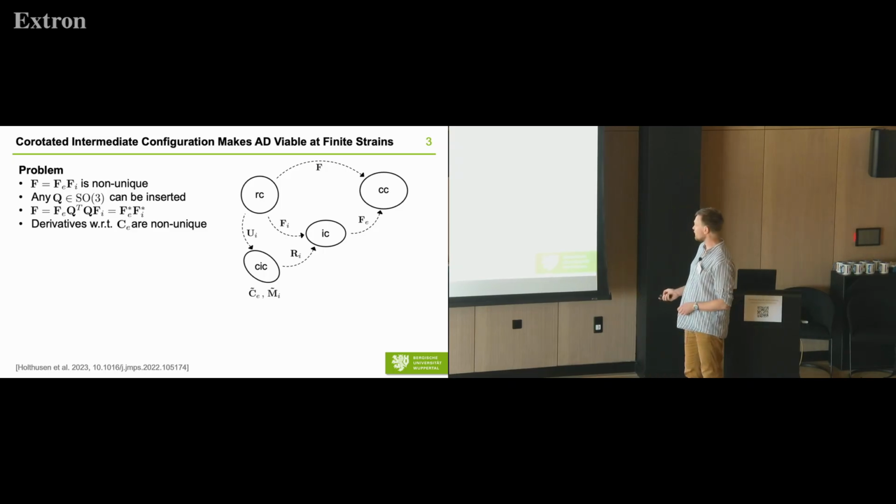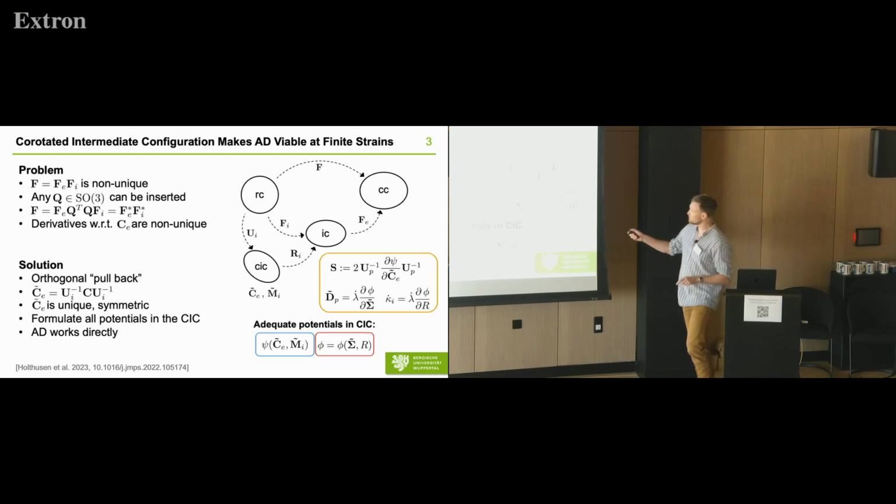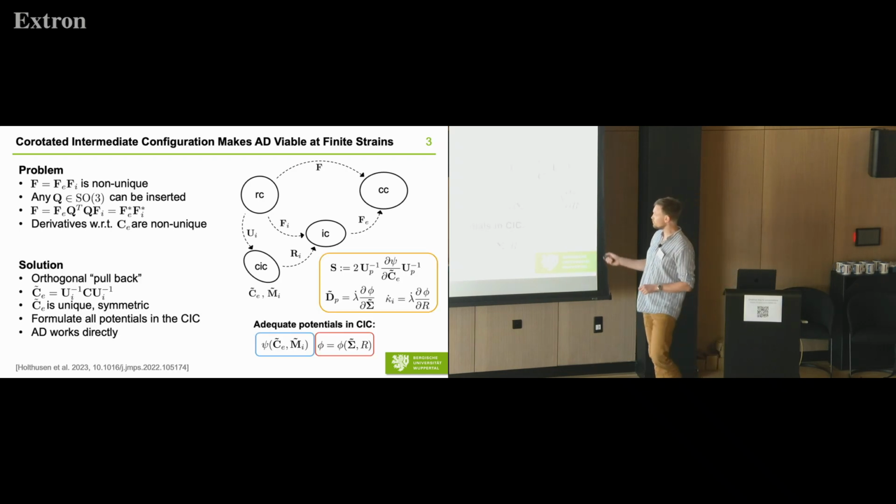I mean, we start with our Clausius-Duhem or Clausius-Planck inequality if we want to be thermodynamically consistent and derive the stress. If we use the Helmholtz free energy, derive it with respect to C. And also for plastic rates, accumulative plastic strain, so all derivatives that are turning up there.